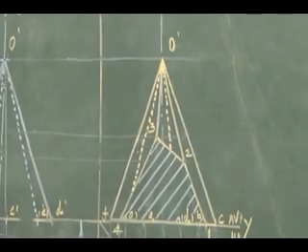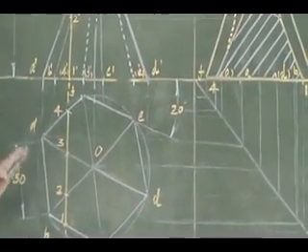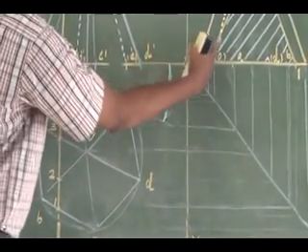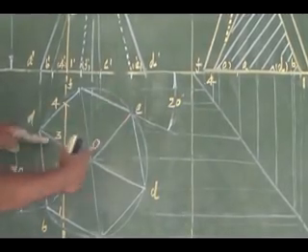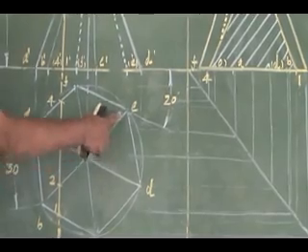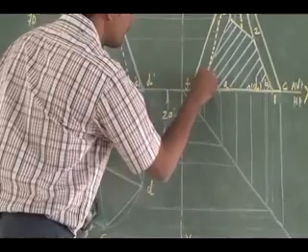So see here, listen, all of you. By removing this portion, I have a hidden line here. So up to this I have shown. Right. The remaining portion also will be hidden. This one, this is my edge. The remaining portion also you have to show as a hidden one.